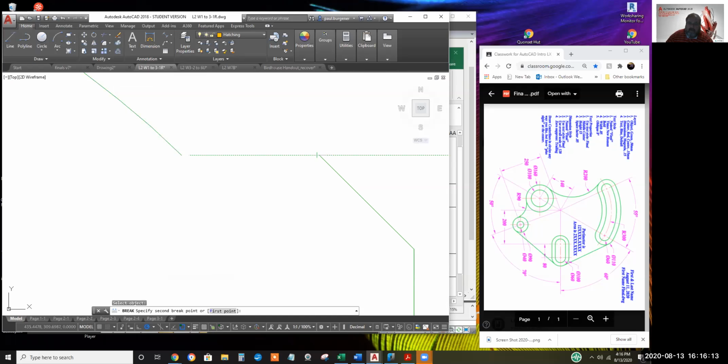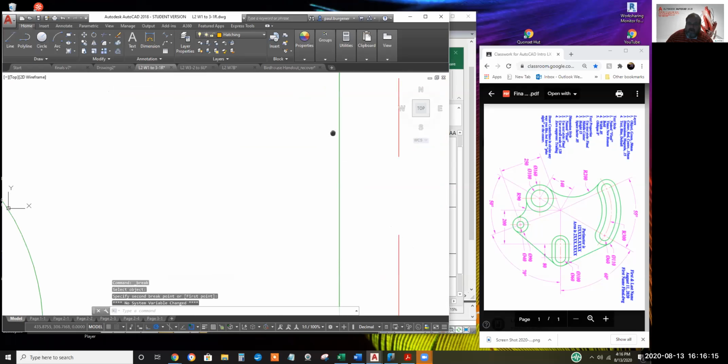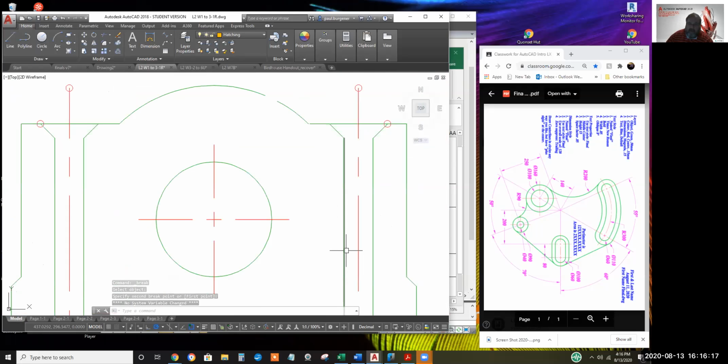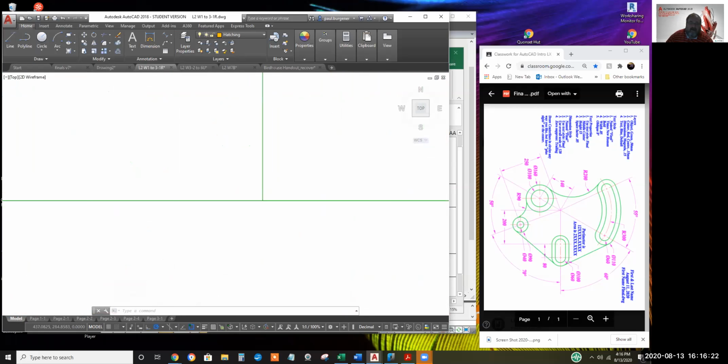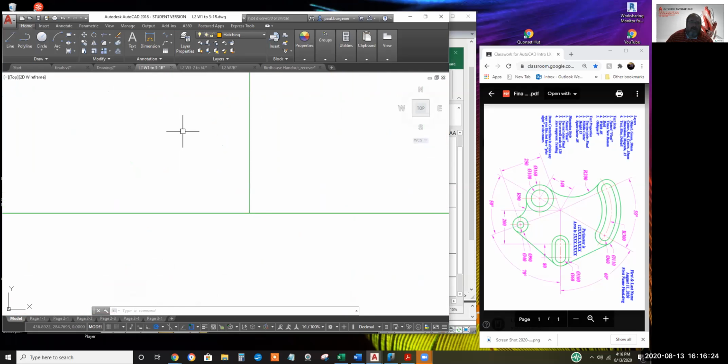So we could use the break command to open every one of the T intersections so that the polyline edit process can work. Probably the closer, the more you zoom in, the less these little gaps will show on the paper.